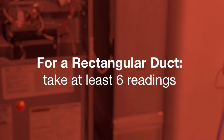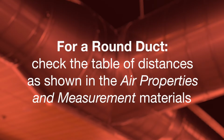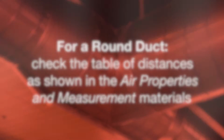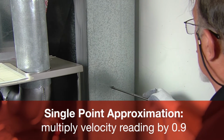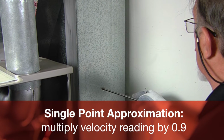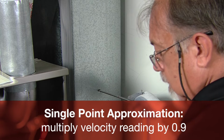For a rectangular duct, you should take at least 6 readings. And for round ducts, check the table of distances as shown in the Air Properties and Measurement materials. As a quick test, you can also take one reading in the center of the duct, known as the single point approximation. However, you must multiply the velocity reading by 0.9.